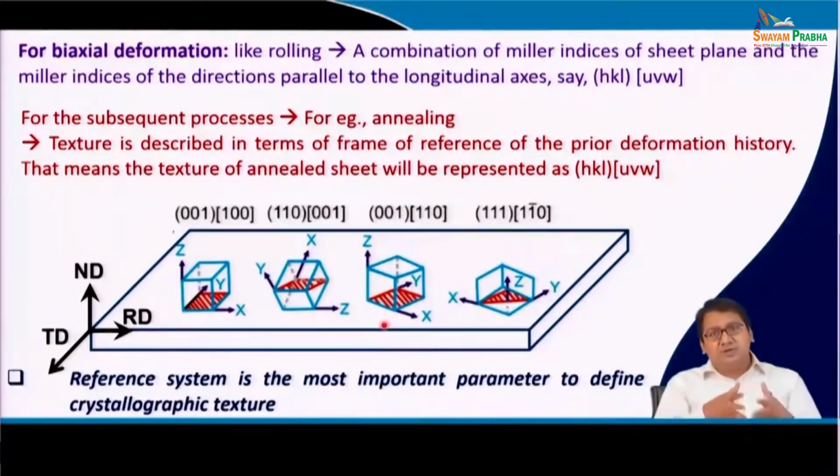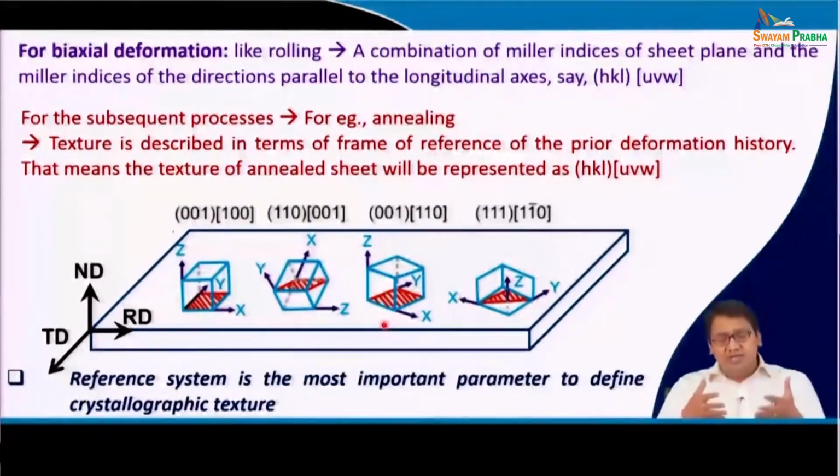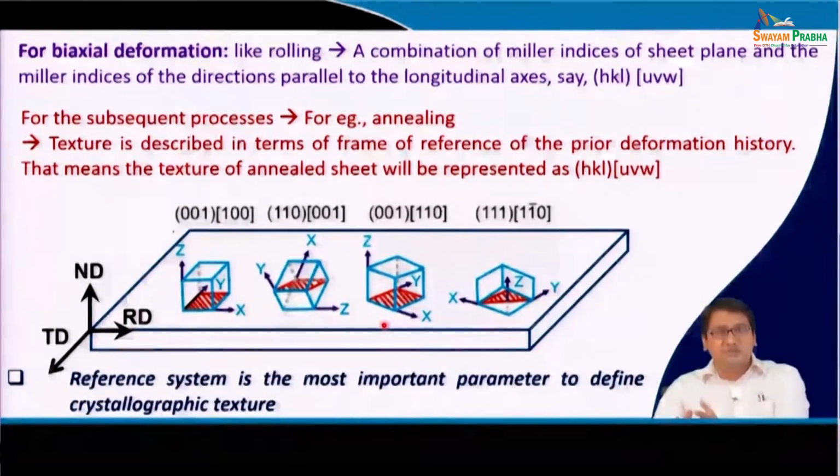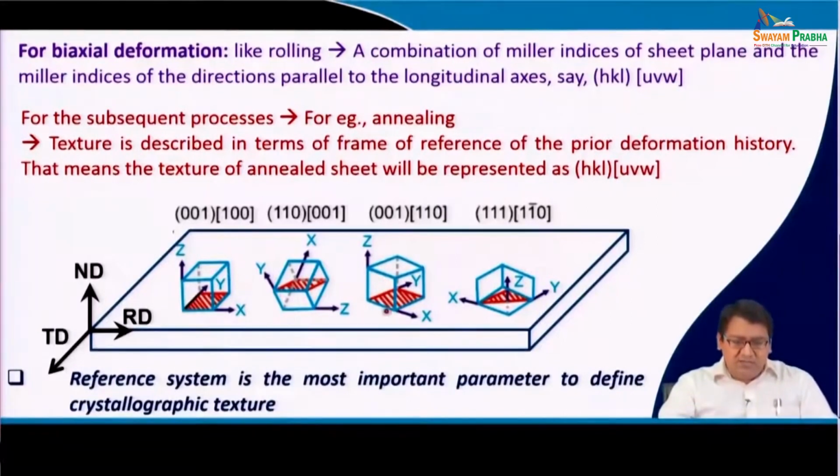And you see that, because the plastic deformation is taking place at a temperature higher than, say for example, the recrystallization temperature, there will be orientations which could be associated with deformation as well as recrystallization. So, in this case, one kind of texture developed, and the unit cell of these grains forming this kind of texture, that is the 111 bar 0 type texture, develops at a higher intensity, say for example, but they are spatially apart.